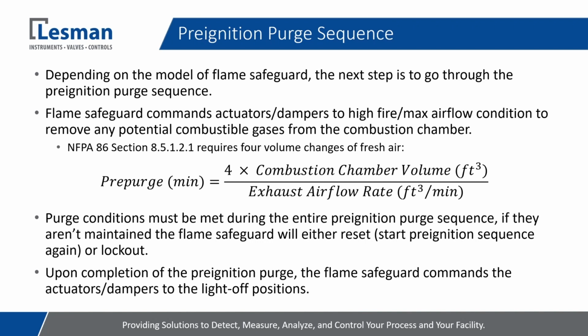But for this example, I just wanted to showcase one of the enhanced controller versions where you need the flame safeguard to command the burner's actuator damper to go to high fire, and it has the internal purge card in there, because you can get stuck in this state. It will prevent you, for those types of flame safeguards, from getting to the pilot flame establishment period.